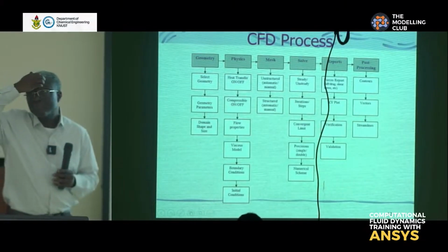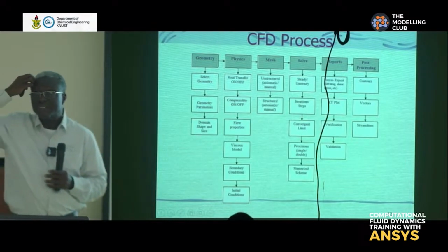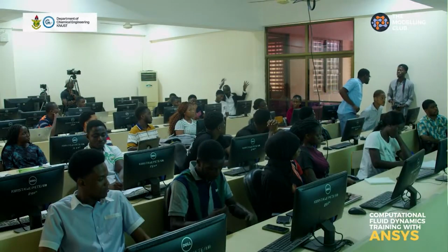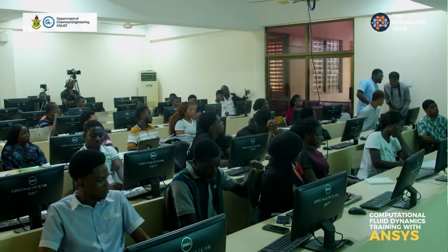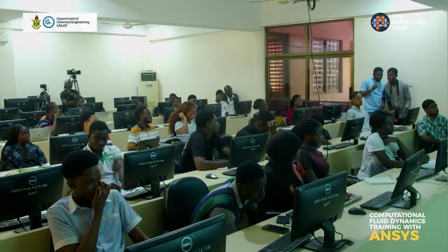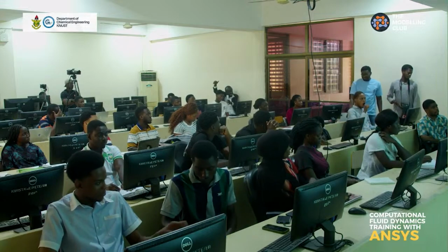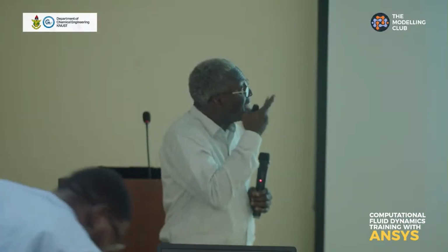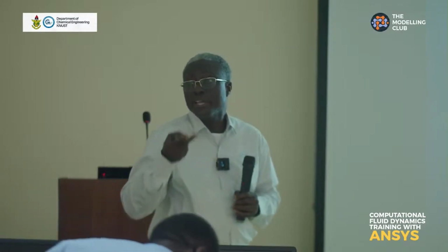Yes? Balance. So you've done, let's say, a reactive system. So you've done all this simulation, but they should base some hardware atomic balance, maybe if it's gasification, let's say. The carbon in the feed should be equal to all the carbon that is out. Is that verification? Yes, that is part of the verification.